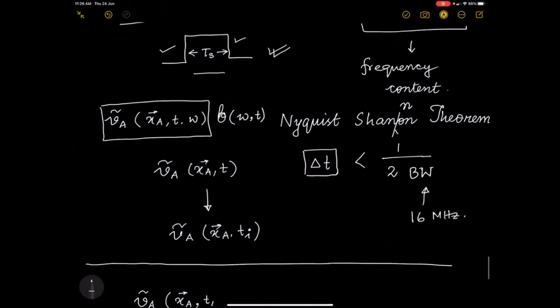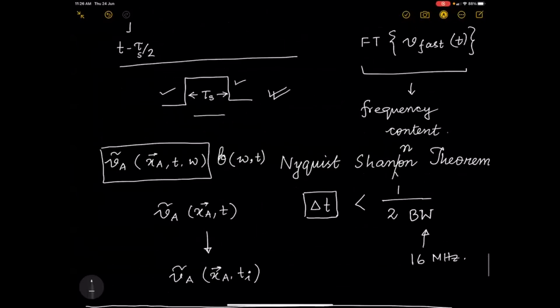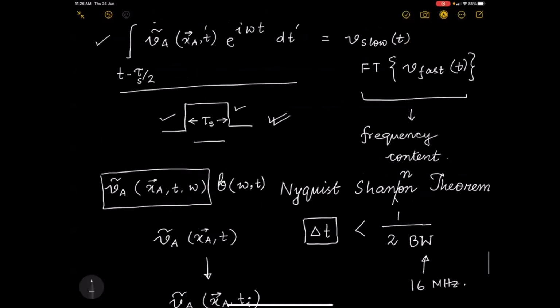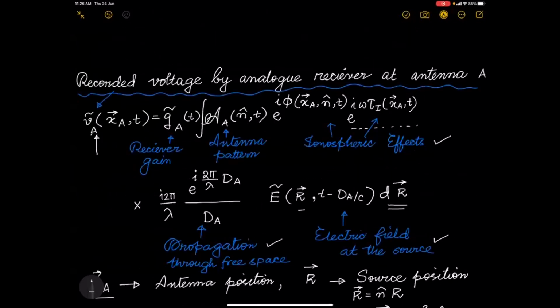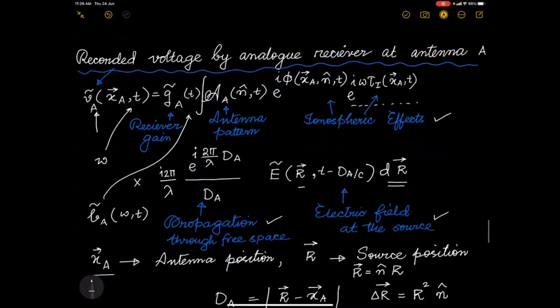So which essentially means that if I want to write down the frequency contents, and I now include nu or omega over here, I need to include another term, which is this bandpass, which can depend on which antenna you are doing, because all the electronics is behind the antenna, and it's a function of frequency and time both. Okay, so I'll come back to it, but let's see what we do with the signal.